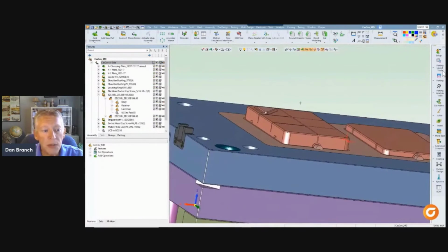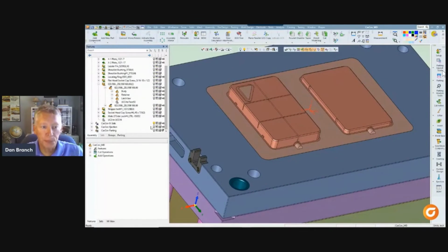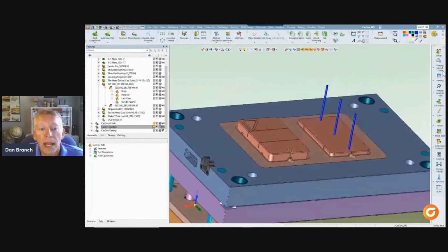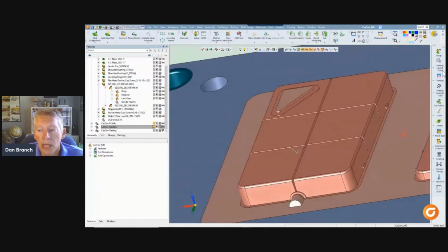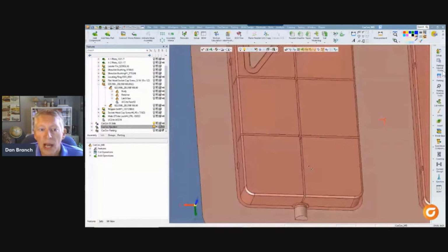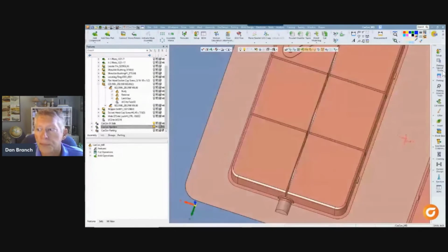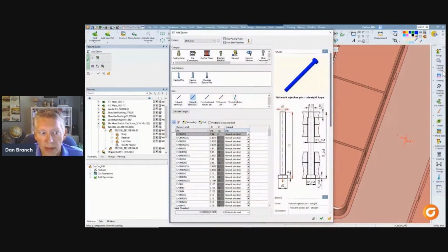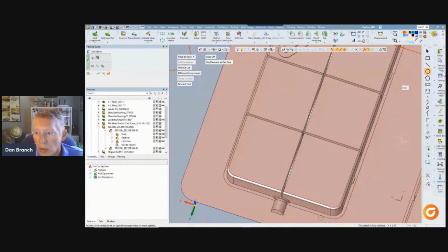So that's cool. Let's move on, and we're going to add a few more components to this design. Ejector pins are very important, of course, and I've already added in a few, but one part has some small ribs in it. And while these need help ejecting, I'm also concerned about trapping air down in those ribs. We head back to the catalog pages. Another new component I can use is the vented ejector pin, and as DME was describing, that fits the bill perfectly here.